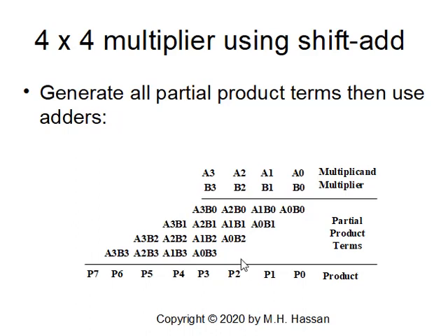So we go on. This will again generate a carry and a sum, which will be P2. When we added A1, B0 with A0, B1 with 0, it gave me the sum P1 and a carry out. So we are adding 4 digits here. 3 digits will generate a carry, so we actually need 2 full adders.